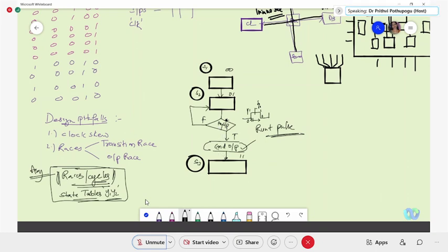That means there is a chance that before generating the conditional output, it may land in a stable state, skipping some outputs that are supposed to be evaluated. That type of error response, we call an output race. Output is not getting generated because of the runt pulse.